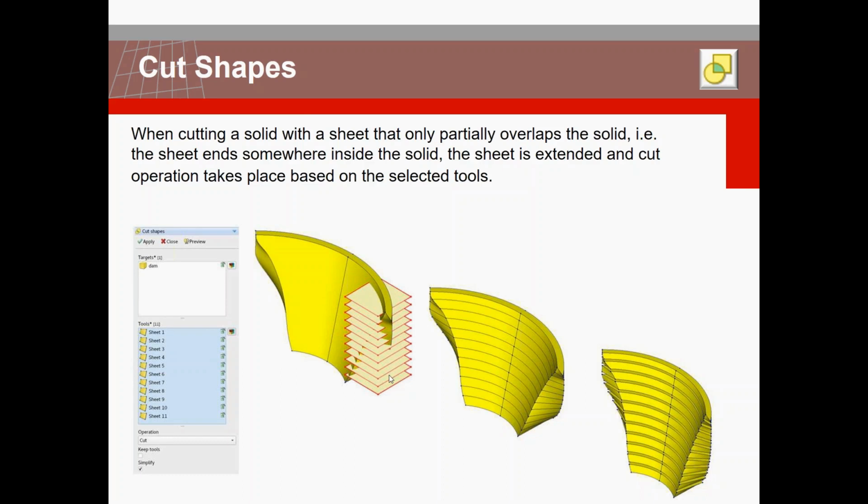What you need to do is define the reference surfaces that you want to cut, and then as long as these surfaces have a little intersection with the reference or target shape, based on the cut shape, it automatically considers the continuation of the inner planar surface per reference surface, and you can easily divide your solid model. So you don't need to define all these cutting surfaces all the way through your solid bodies. This is a very nice and optimal way of operation in the model.